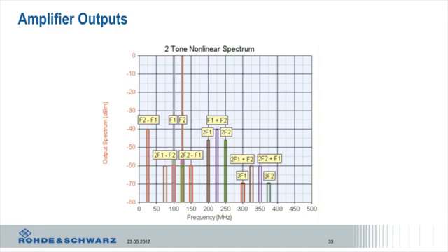When you're designing a complex system, you're going to find that you need to be able to take these things into account and process and put in filters and things adequately. But if you have a broadband system, you're not going to be able to filter these out. For example, like a TV receiver, where you can't filter them out because you need to be able to receive all of those channels from a low frequency to a higher frequency. Okay.